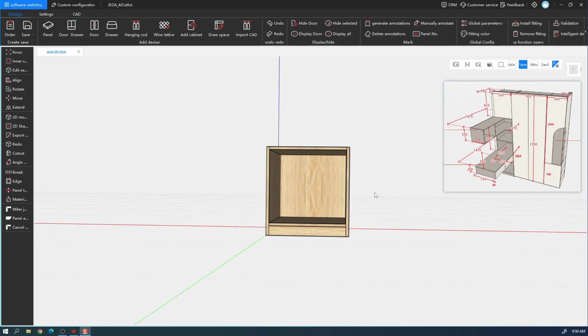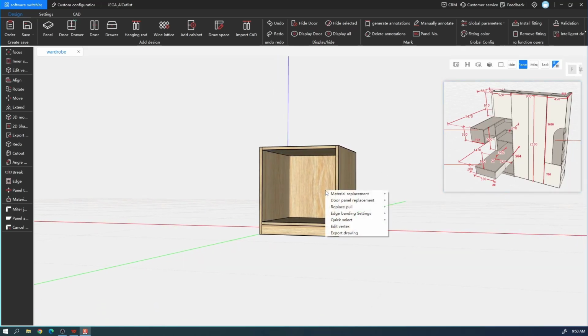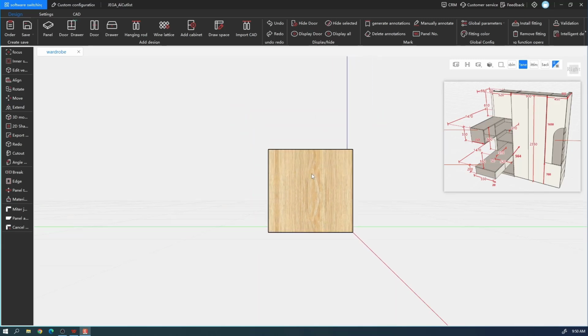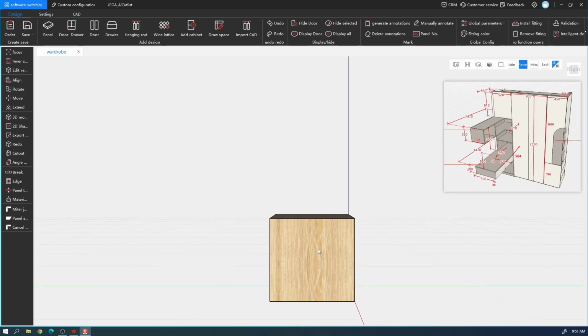So we just rotate our view to the right side first, and then go to the upper right corner to find this cube and click this right. Then we will change to this right view. Under this right view, when we create some cabinets or place some shelf inside, the system will consider this view as the front view. So like now, let's add one.